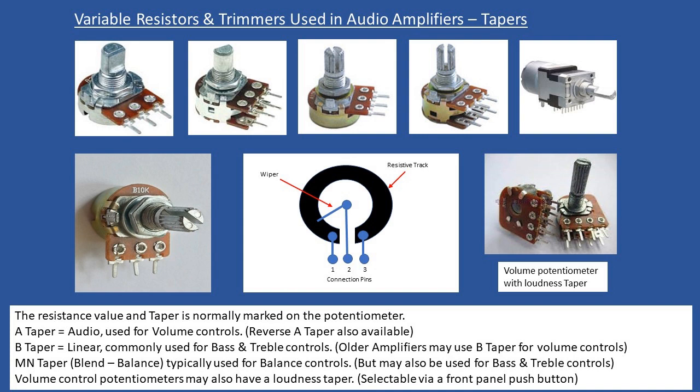And a lot of amplifiers have a loudness switch on the front. I'm thinking, for example, maybe a Denon amplifier or even a NAD amplifier, some of the earlier ones. You get the volume potentiometer out and it's like 20K, and then you look and think, well, there's a 4th connection here, so that's fine. I'll just put a standard one in, which has got 3 leads on or 6 leads. But what you've done then is you removed the operation for the loudness function.